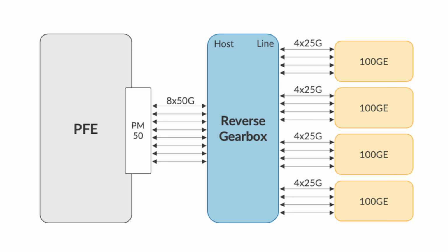And in other configurations, a PHY can be used to create a larger fan out and increase the port density of your routing device. For example, in reverse gearbox mode, we are converting 50 gig SerDes on the PFE side into twice 25 gig SerDes on the interface side. The conversion includes the re-encoding from PAM4 to NRZ and different error correction on each side.